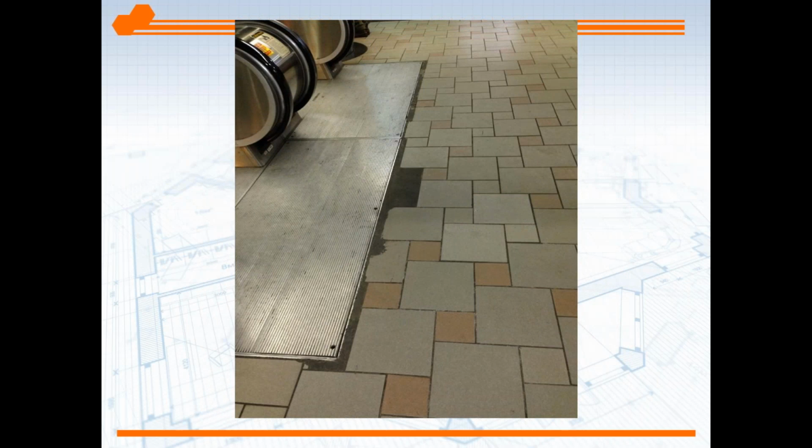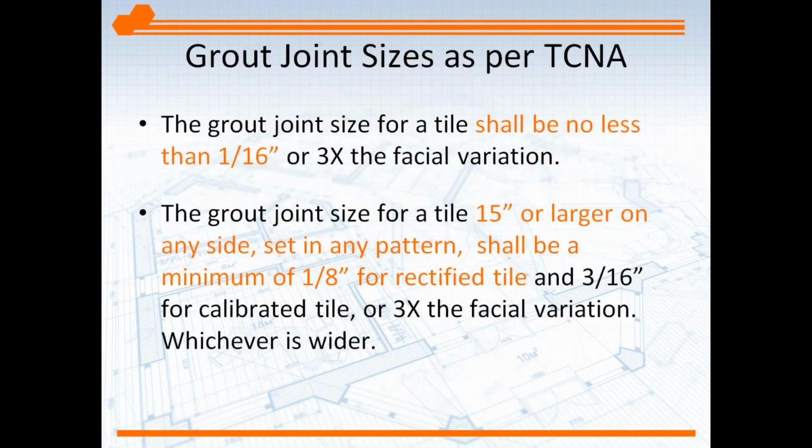Around the area that's dissimilar, you have the metal, you have the tile. You're going to need a soft joint in this area, and you can see the ramifications of not putting that soft joint in. Not only did the grout get destroyed here, it started to disintegrate the tile because the edges are exposed. So again, soft joints around the perimeter of any tile installation are critical.